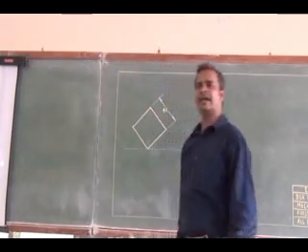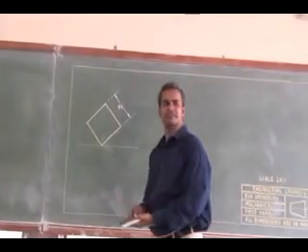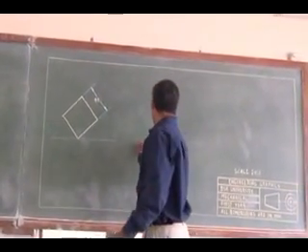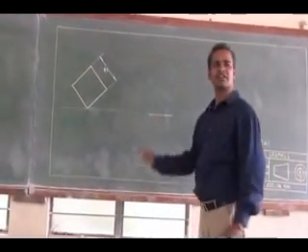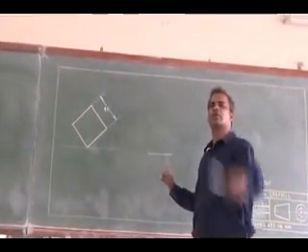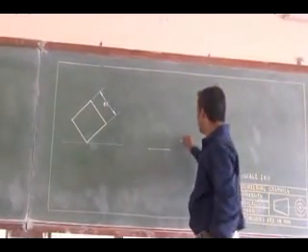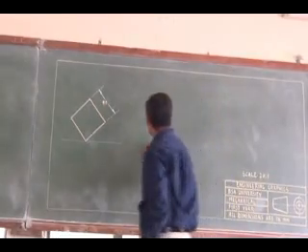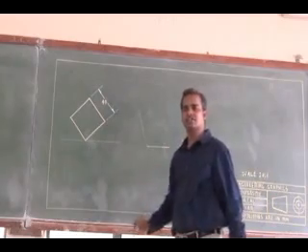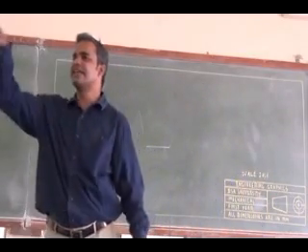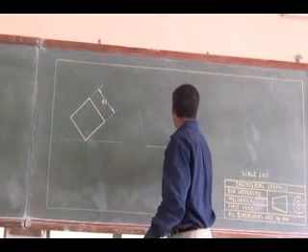You see here, how can I construct the pentagon? The pentagon has 5 sides. So I can draw one side of my pentagon like this. This is 30 mm, this is horizontal. Right? Listen all of you. One side is horizontal, this is 30 mm. Then the other side I have to draw it like this. So what will be this angle? 72. How is it 72? 360 degrees divided by 5 sides. So that is the angle. So this angle will be 72 degrees.